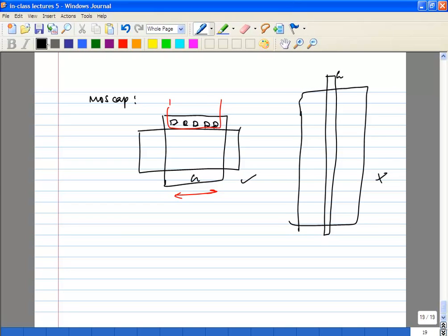And again, for all of these caps, because you're trying to get a lot of cap, let's say if you take a decoupling cap, more cap is usually always better. So you don't care about parasitic caps. Don't worry about stacking metal layers on top of the decoupling cap. Extra cap only helps you, right? You want to minimize the resistance, so try to stack as many metal layers as possible.